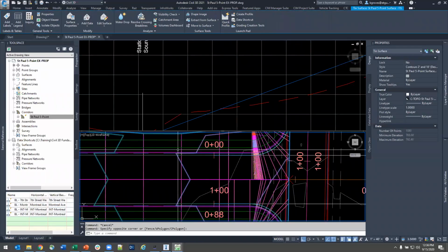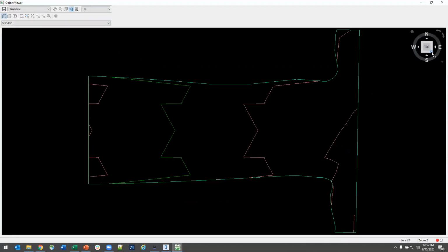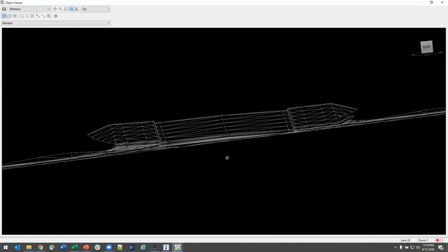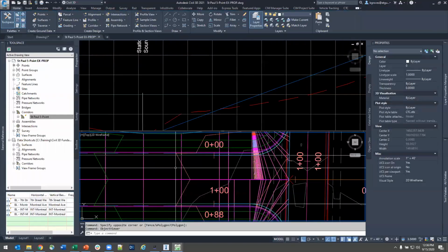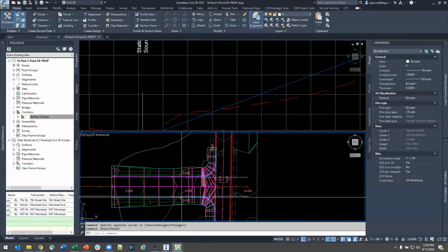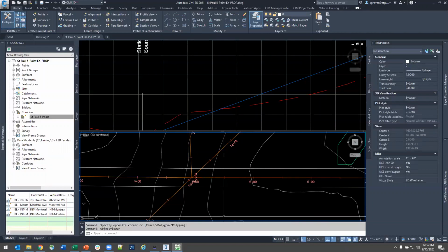And now I can see, again, these contours are all smooth. So that was my design check. So having your surface created is going to make it really easy for you to confirm that everything is happening the way that it should be. Those contours should be relatively smooth, well, where they should be relatively smooth, in this case, across my lanes. So that's proposed to existing intersections. And technically, you could find a way to apply all of that now to the rest of this 5-point intersection.